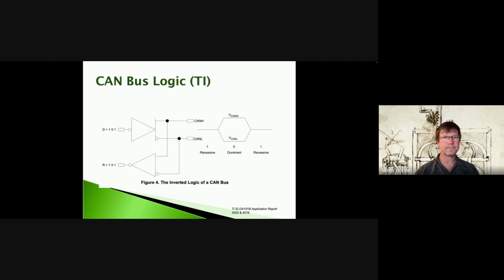All right, so here's a description from TI of this kind of inverted logic. In the recessive state, we're not holding the bus at any particular point, but in the dominant state, you'll note that it's active low signaling.